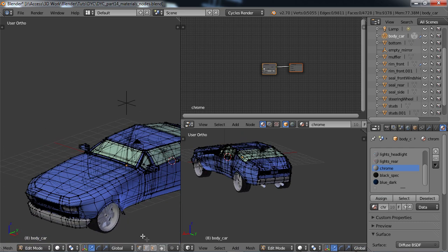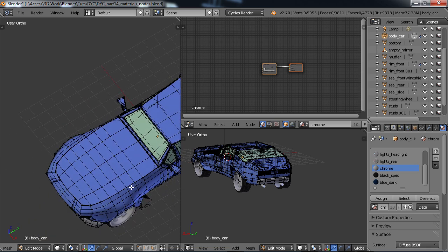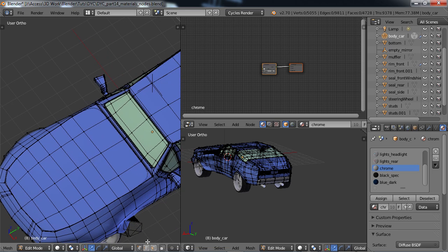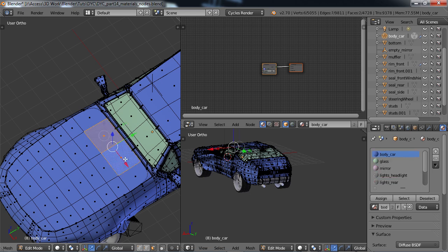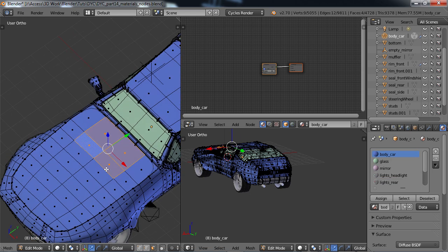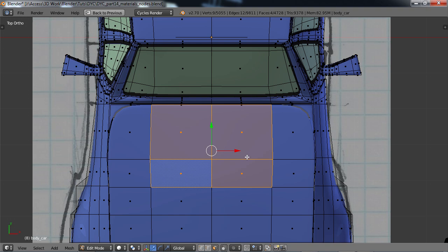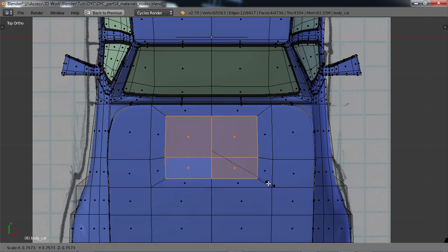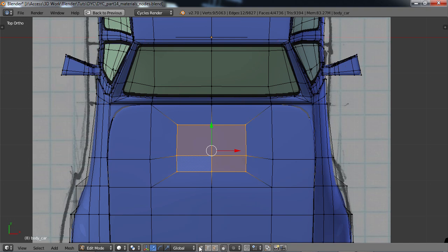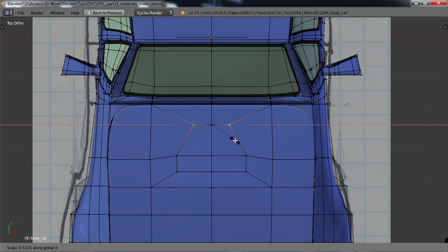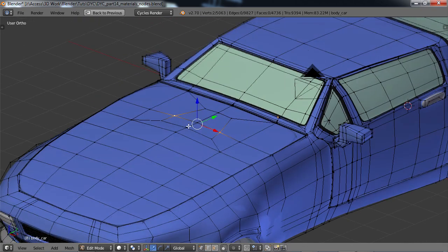and we do some sort of spoiler here. We can come in here and face select. Just going to select all these faces right here. 7 top view, control up arrow. E-extrude, scale down. And we'll say that, let's see, spoiler maybe about that big. Choose Vertex Select. Choose these 2 vertices, SX, scale these down like so. These 2, SX, scale down like so.